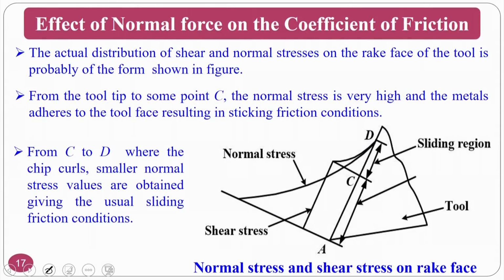Okay, the actual distribution of shear and normal stresses on the rake surface of the tool is shown in the figure. So if you can see, this is the normal stress and this is the shear stress. Okay, so this is the sticking region, and this is the sliding region.